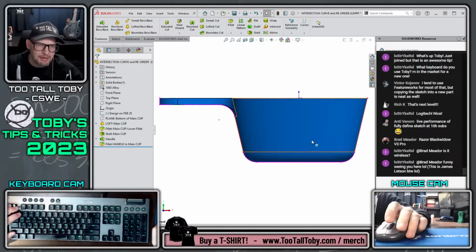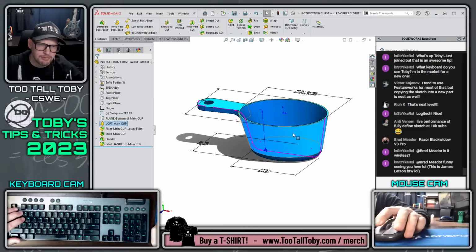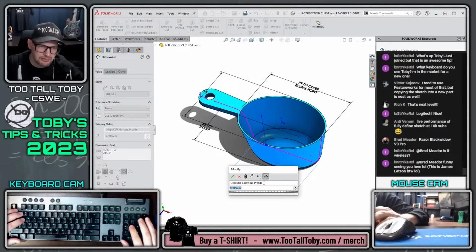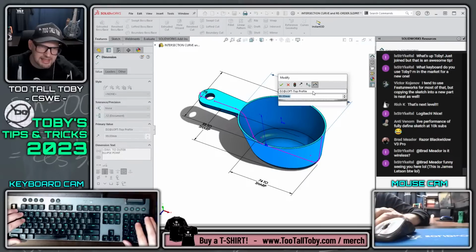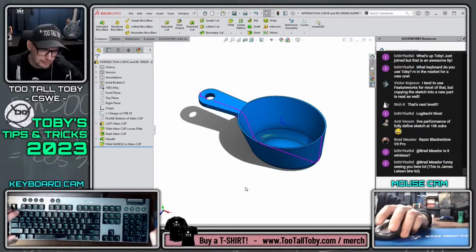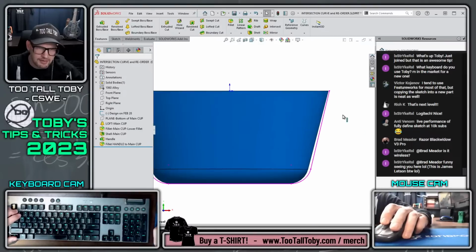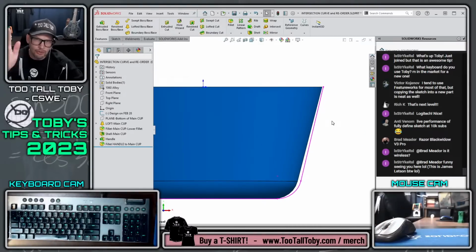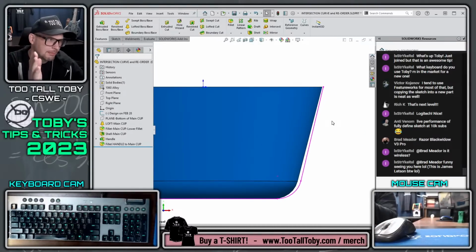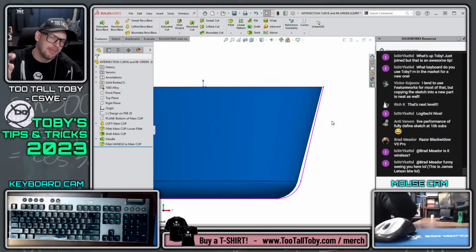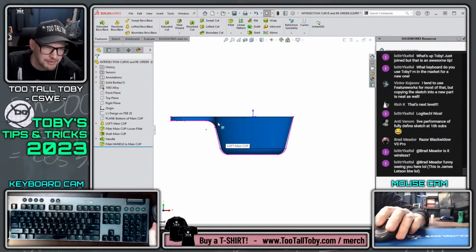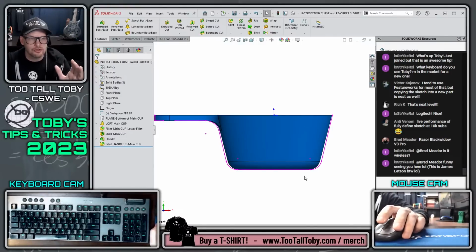And then if I am working with the customer, we're doing a design review, and we say, let's change this to 74, and let's change this to 98, and let's see how that looks. And so we could do a Control Q, and then we could go to our front view, and we can see, oh yeah, that's nice. The angle's a little bit greater. It pulls in down at the bottom a little more. I like that. Let's go with that design. Let's 3D print that and see how that feels. So it's just a cool little trick that I like to use.